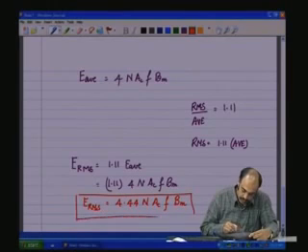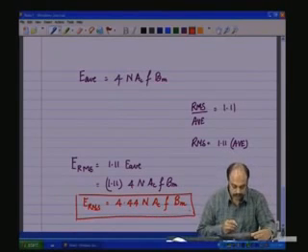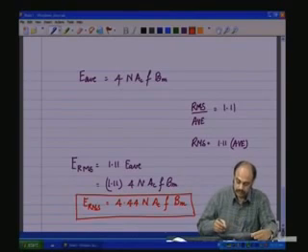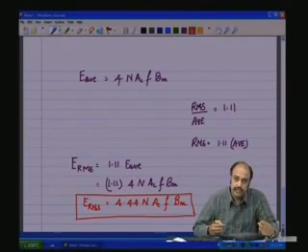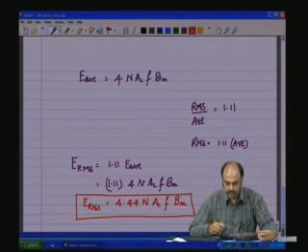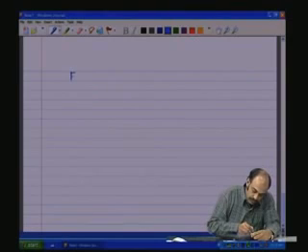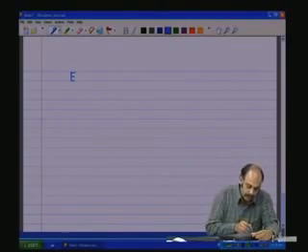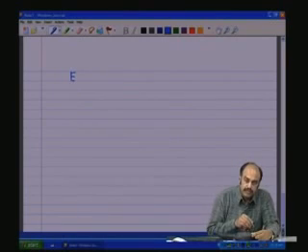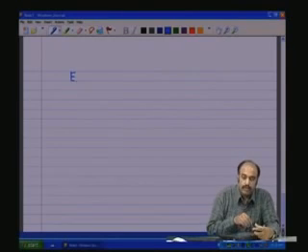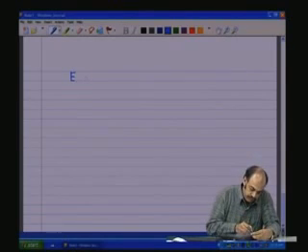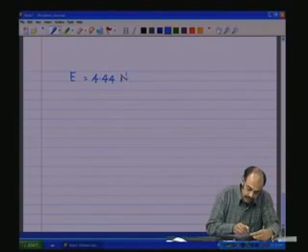This is a pretty important voltage equation for the transformer, or the voltage across a coil when we are talking of sinusoids. Looking at this equation, if we don't put any subscript on the voltage E such as RMS, average or peak, it automatically means the effective or RMS value, given by 4.44 N Ac f Bm.